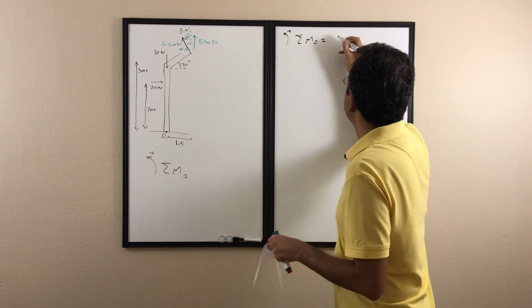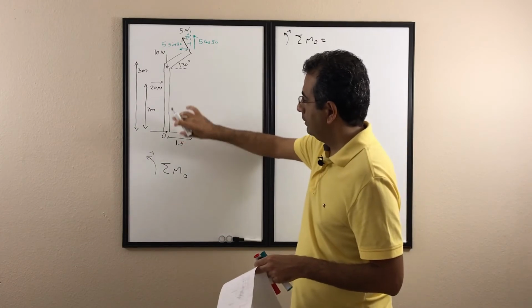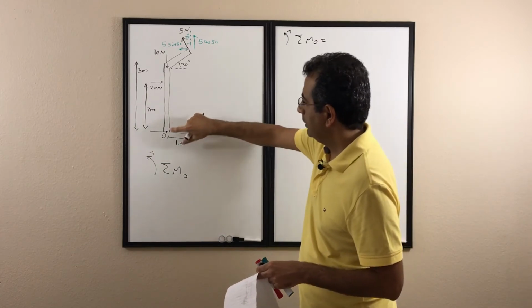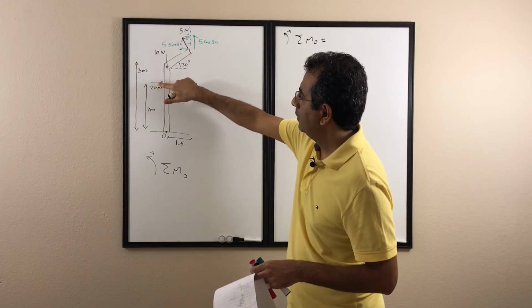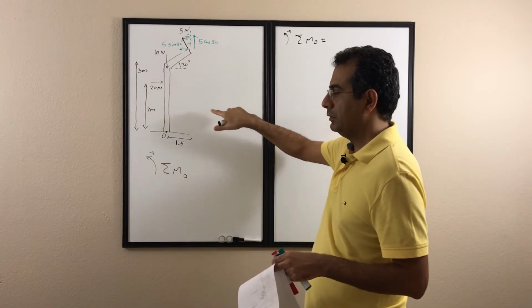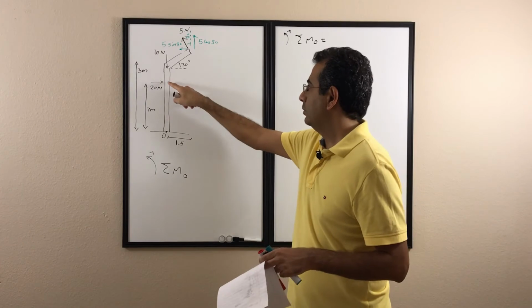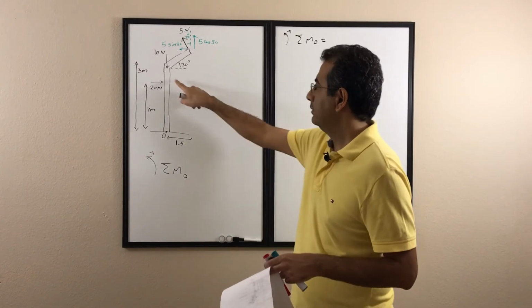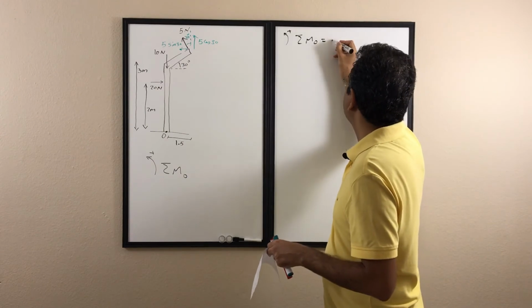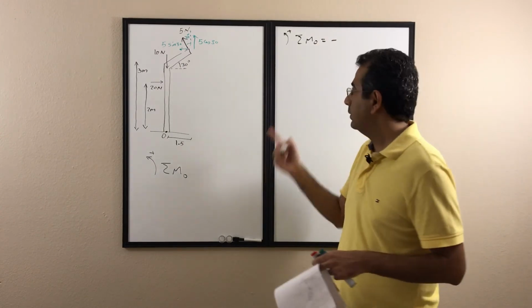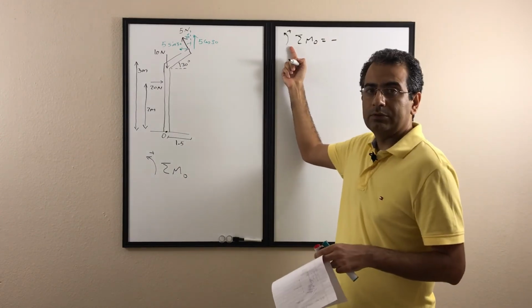the 20 Newton. So is it rotated clockwise or counterclockwise? Again, if I connect a rope from here to that force and see which direction is going to rotate that rope, it is going to rotate this direction. So it's going to be clockwise. Because of that, it is negative, because I consider counterclockwise to be positive.